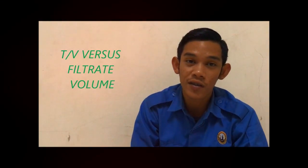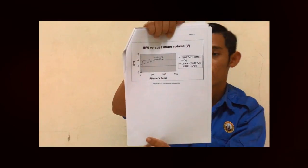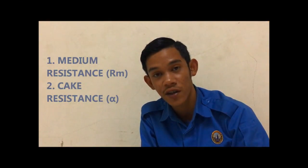Based on these results, we can make a graph of t over V versus the filtrate volume V. It will be like this. In this experiment, we have to calculate the medium resistance of each tray and the cake resistance of each tray. So for the medium resistance calculation,